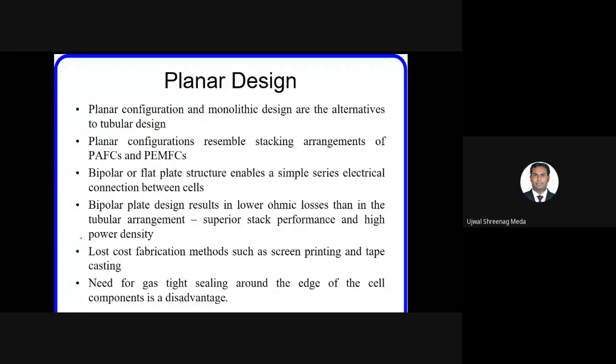Now coming to the planar design. Planar configuration and monolithic designs are the alternatives to tubular design. The stacking arrangement is very similar to the other fuel cells such as PEMFCs or PAFCs in the case of planar configuration. In planar configuration, bipolar plates are necessary, but when it comes to tubular design, it will be an interconnect.